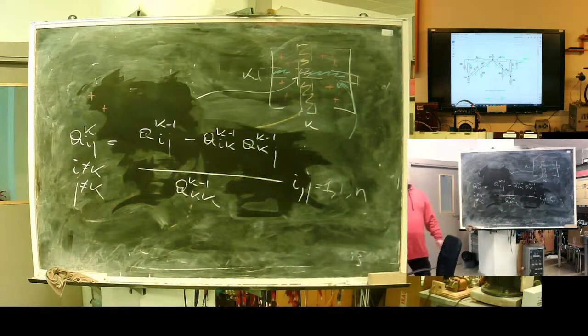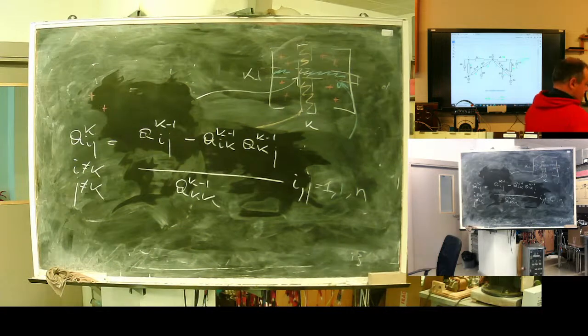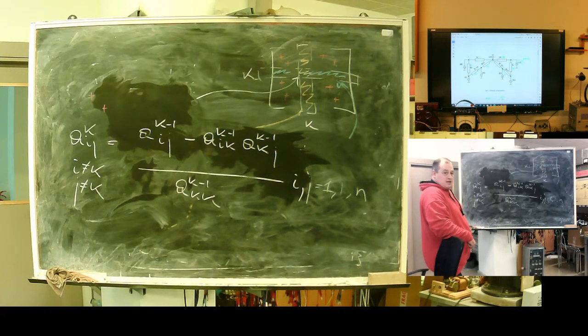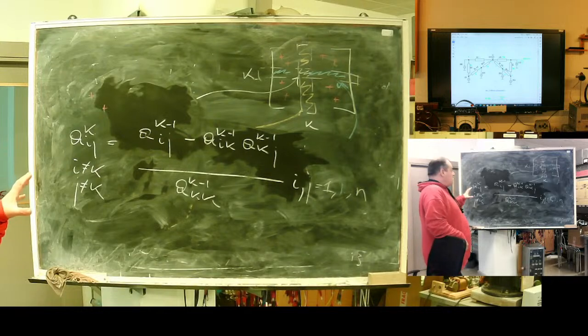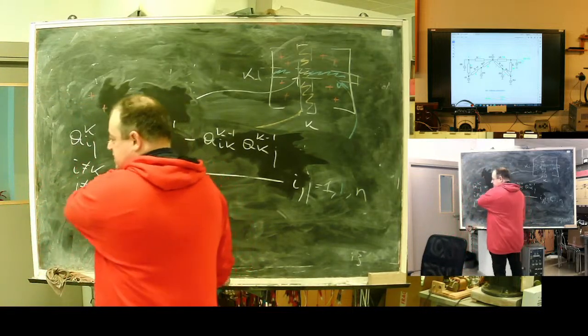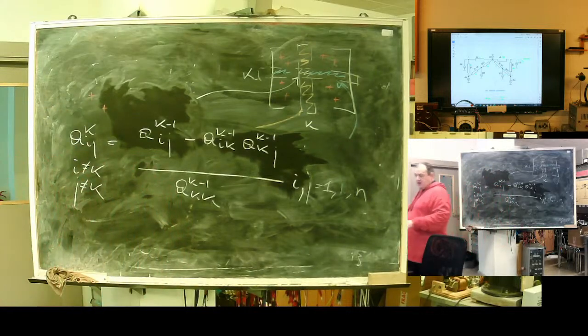This is Jordan's inversion technique. It allows us to obtain the inverse nodal admittance matrix. It works both for AC and DC networks. It's a way to boost performance. It's a bit tricky because Jordan's process itself requires n cube operations.